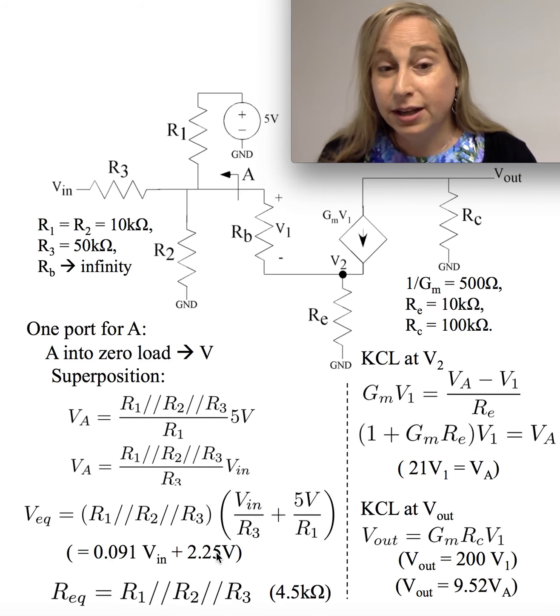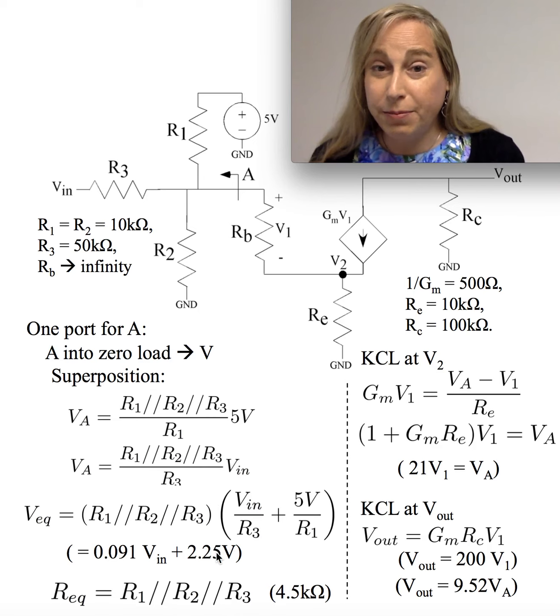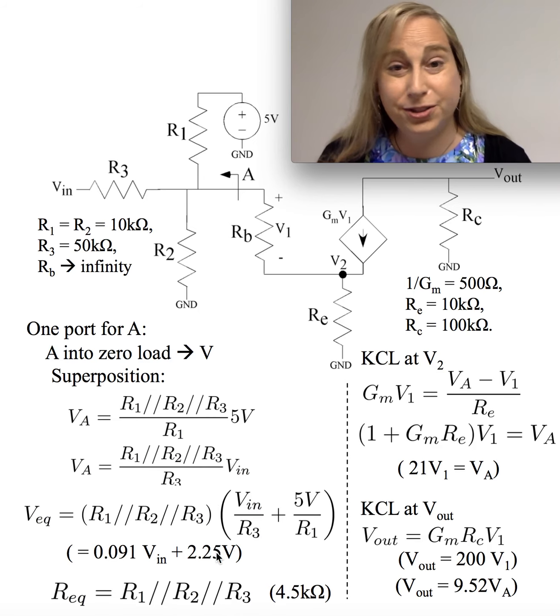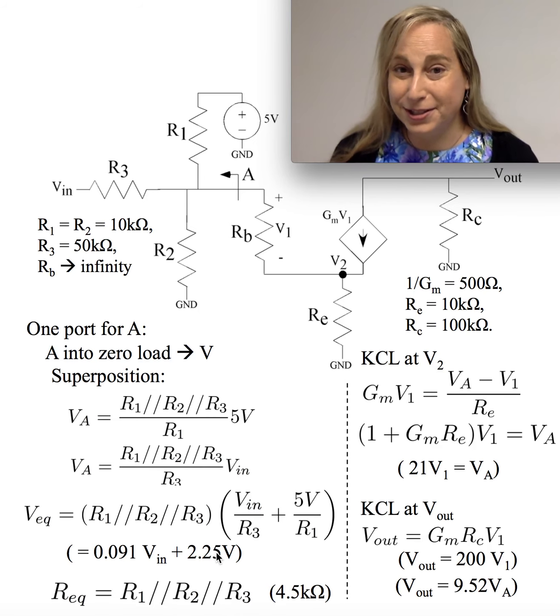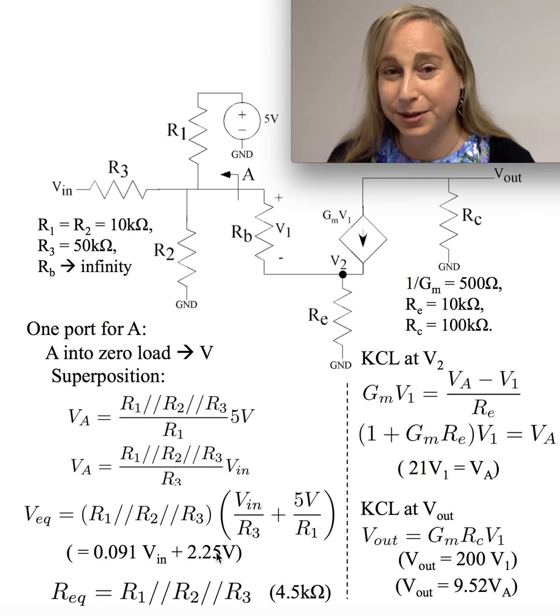and these would be the numbers I would see as a result. A lot of times we want to know that because we're setting up all these resistors and voltages to bias, say, a voltage-controlled current source, which you might also think of as a transistor, because transistors do that pretty well. There are other ways to do it, but they do that very well, and it's about how you set that in the right place.